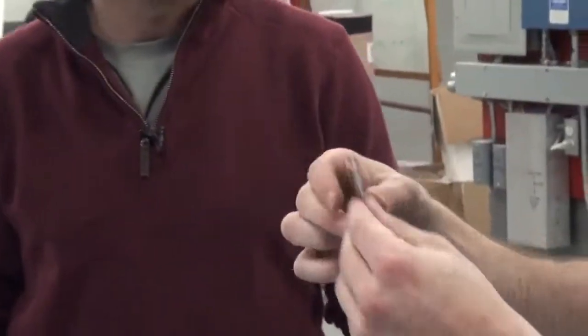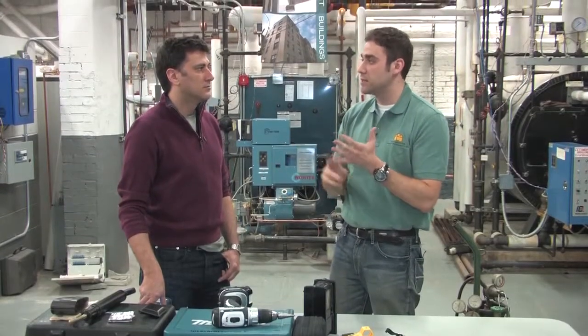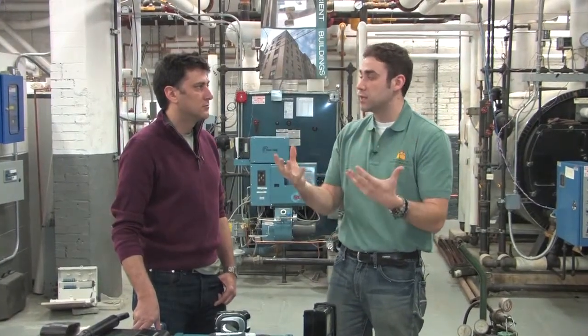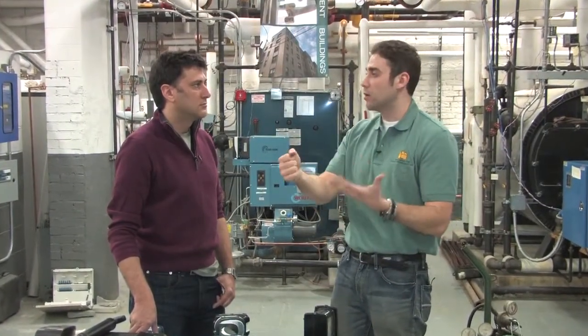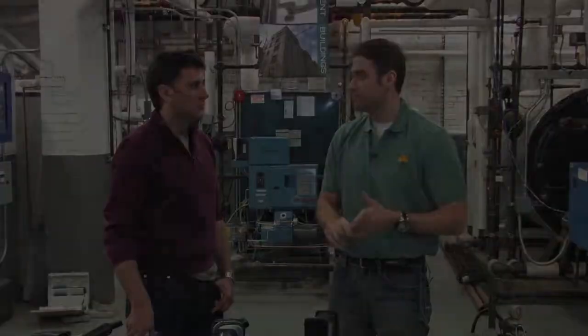Afterwards, we use a UL approved metal tape, and this way that can be plugged up afterwards. If it's B-vent, you want to drill into it. If it's PVC or stainless steel, you don't want to drill into it. But if it's a single wall galvanized pipe that's used on an atmospheric system, we can go ahead and make our hole and do our testing, and we'll be okay.